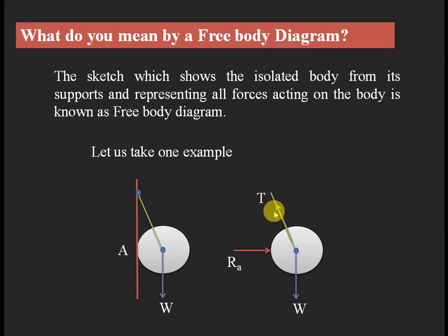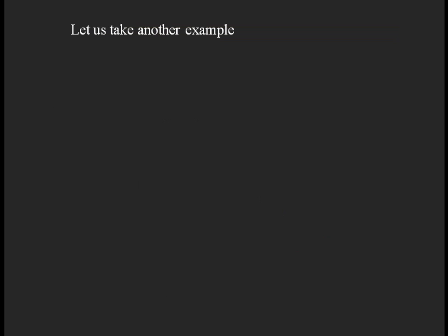So here I have isolated the body and represented all the forces acting on the body. This diagram is known as a free body diagram. While solving engineering problems we can apply this knowledge for getting the desired values of the loads and the distances at which they are acting. Similarly, we take another example.